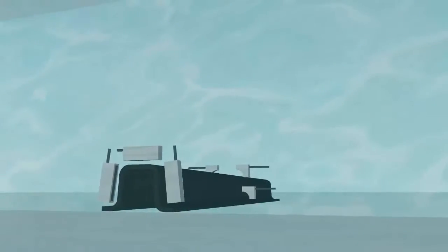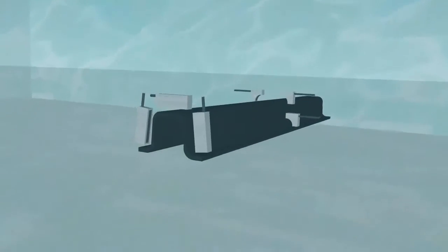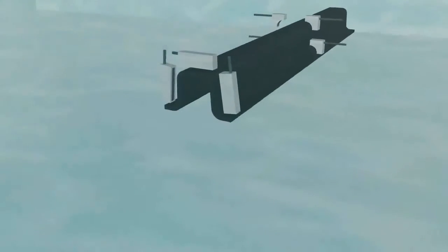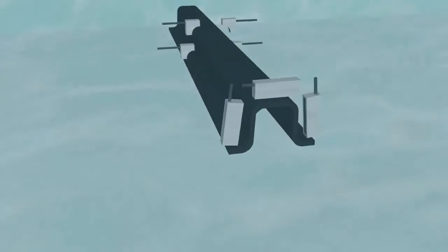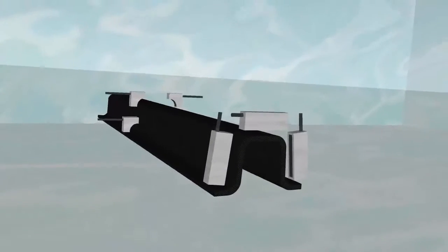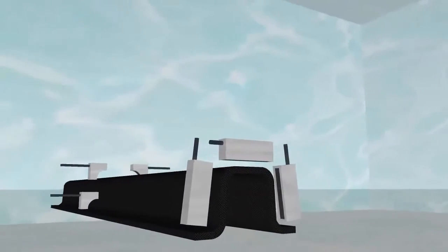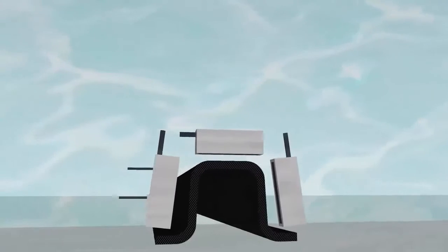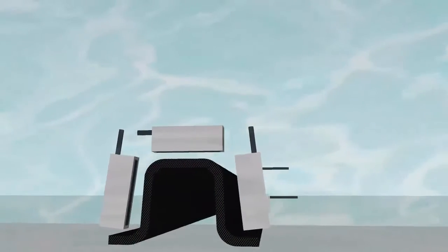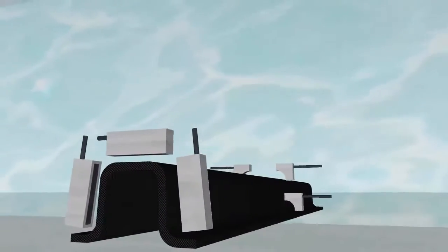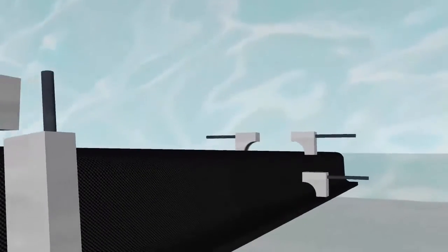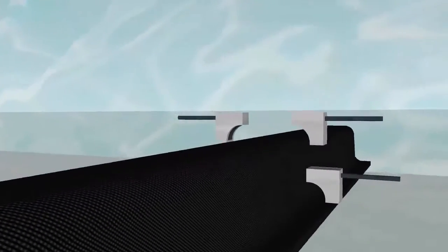To optimize the detection capability, the probes must be carefully selected according to the specimen geometry. The inspections are performed essentially at a normal incidence with the component surface. For the typical composite shapes, this typically requires a combination of two types of probes. A linear 1D phased array probe is used to inspect flat surfaces. These probes typically have 32, 64, or 128 elements. For curved sections, arc-shaped 1D probes are used, with typically 32 or 64 elements.